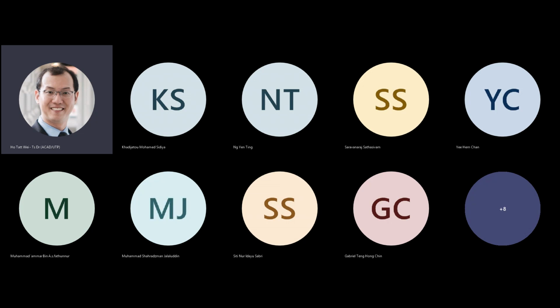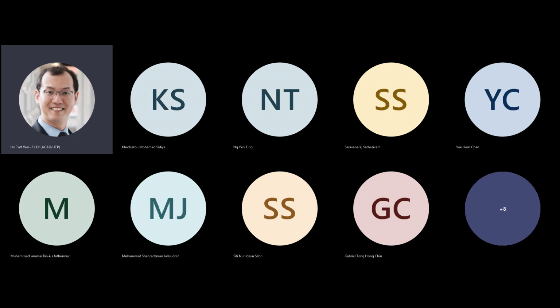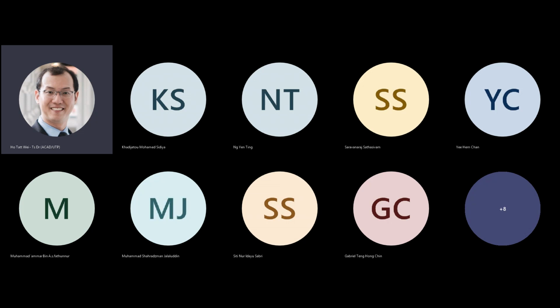And also in this part here, at some point in the saturation, the velocity saturation regime, this alpha is going to be closer to 1.2, 1.3 thereabouts. But the temperature dependence of the current is actually going to be here. The T is coming in by influencing the mu here.